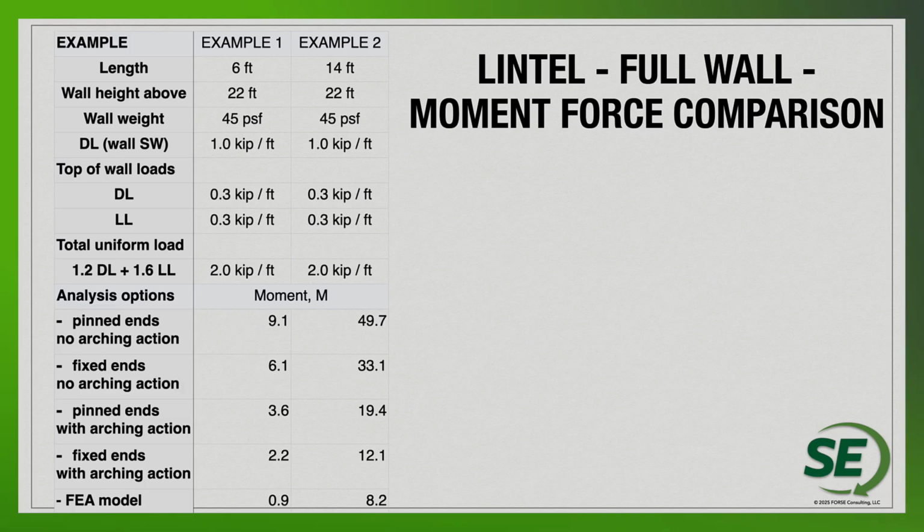Now, if I look at pinned ends with arching action and fixed ends with arching action, you can see that the moments continue to drop considering all the different options. And then again, we can look at how the moment correlates to the finite element analysis. You can see fixed end with arching action corresponds pretty well with the finite element analysis.